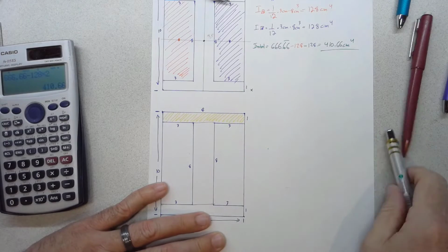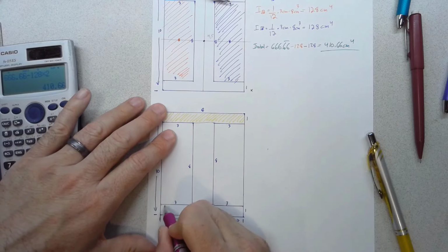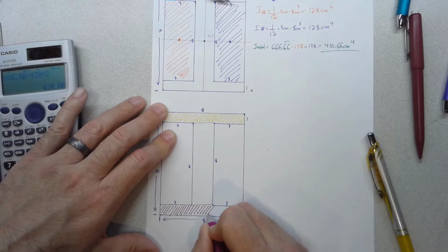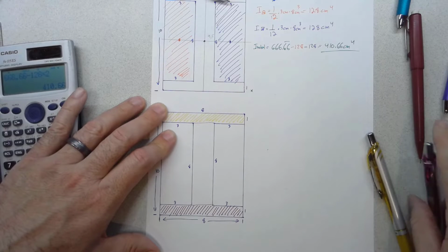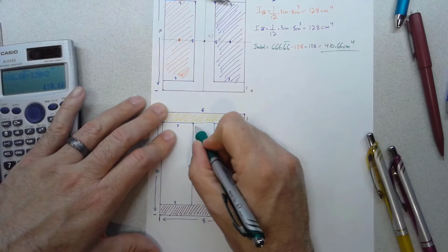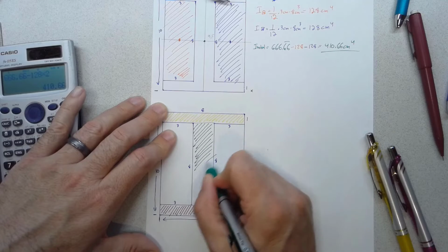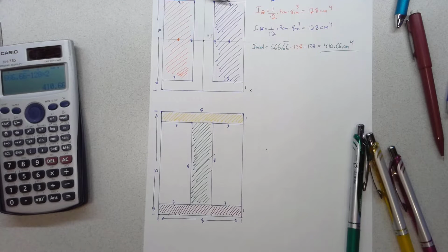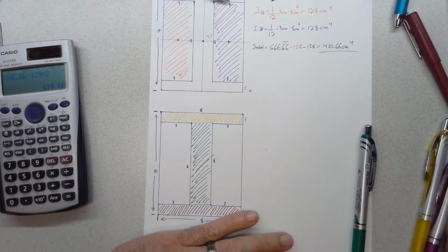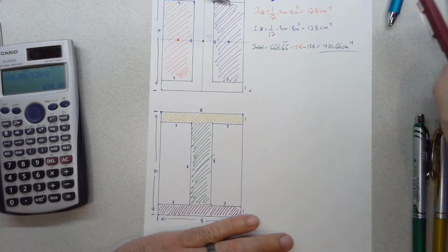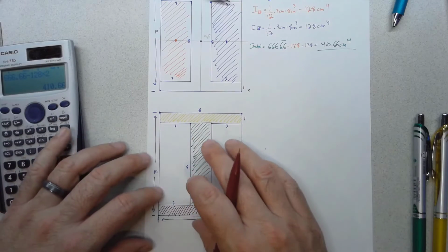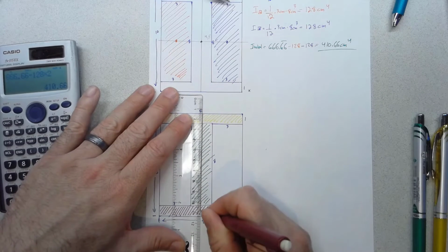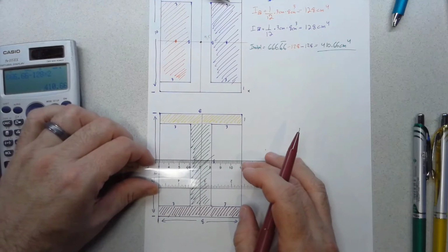It's an area in yellow. Okay, so now we've got 3 areas. So let's go ahead and find the contribution that each of these 3 areas make. And we know that the neutral axis, or the centroid of the final shape, hasn't changed, right? It's still symmetric about a line right down the middle. And then we know the centroid's going to be also mirrored this way across here.